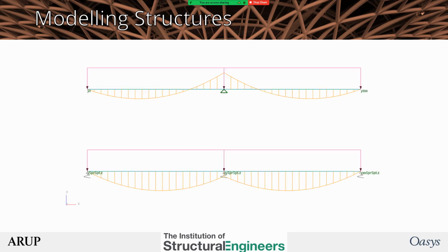So some moment redistribution occurs because of plasticity, but a lot will occur because of the error in assuming that support is infinitely stiff. Model the ground with springs, or support with springs, and you'll notice the sagging increases, hogging reduces, and so on. And likewise, the retaining wall model I did back there would also give correct bending moments in the base.